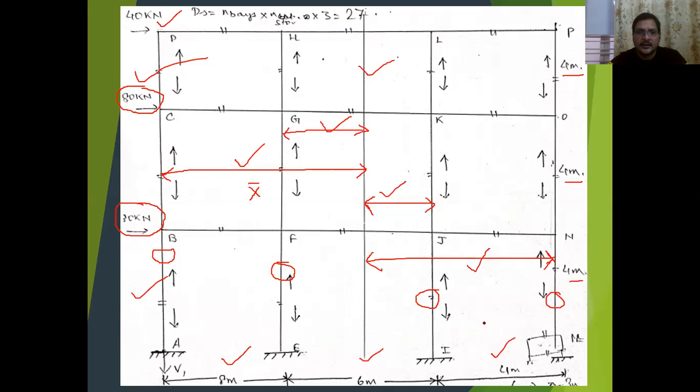Since I require the distance of all the individual columns with respect to the line of CG, we have to find out the distances. Also, the CG line particularly, we have to draw using a pencil beforehand, because we might make some mistakes while drawing this line with a pen. It is better to use a pencil, because we don't know the distance of this CG before calculation.